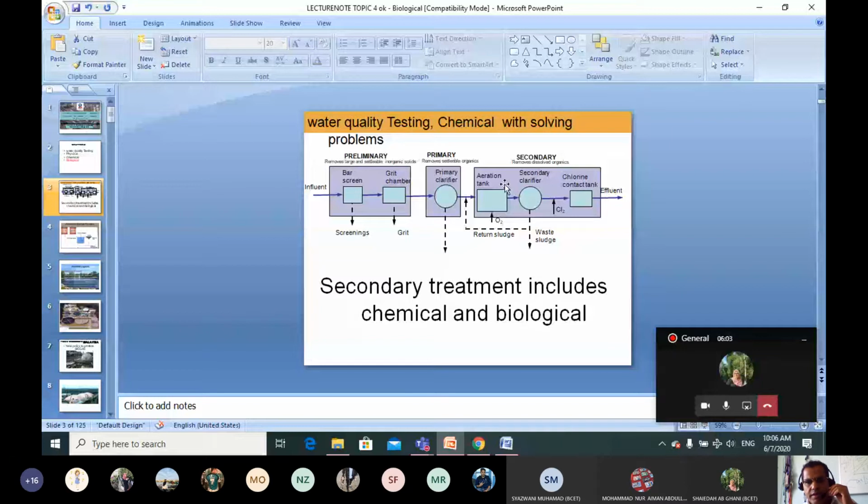And here, if you see this area, we make aeration. What do we mean by aeration? We introduce oxygen through air pumping, and then mixing. So bacteria utilize oxygen and also break down hydrocarbons, either nitrogenous compounds or hydrogenous compounds, and then it becomes clear water, and then goes to the final stage.